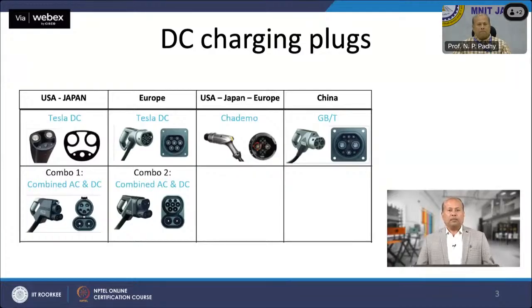With respect to car manufacturers, American, European and Korean manufacturers have adopted CCS combo, and Japanese manufacturers have adopted CHAdeMO. As the number of EVs is growing day by day, the adoption of new technology has seen exponential growth. Hence, the stated charging connector list is indicative and will change over a period of time.